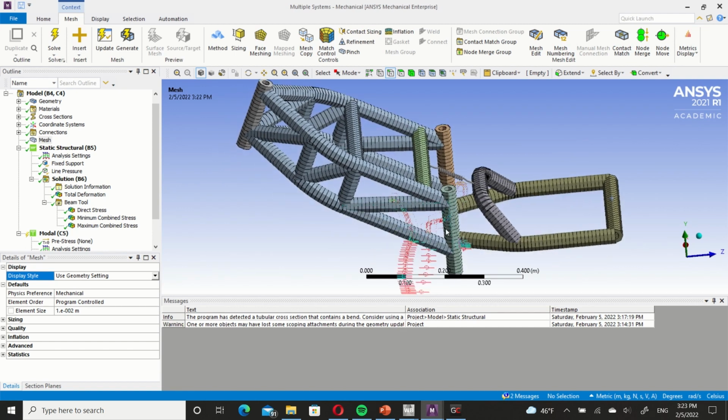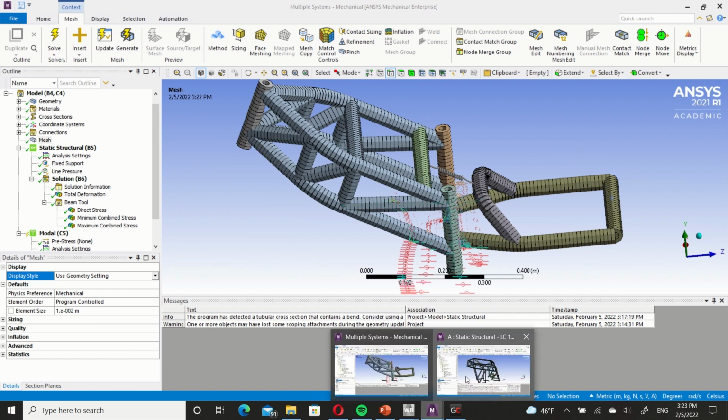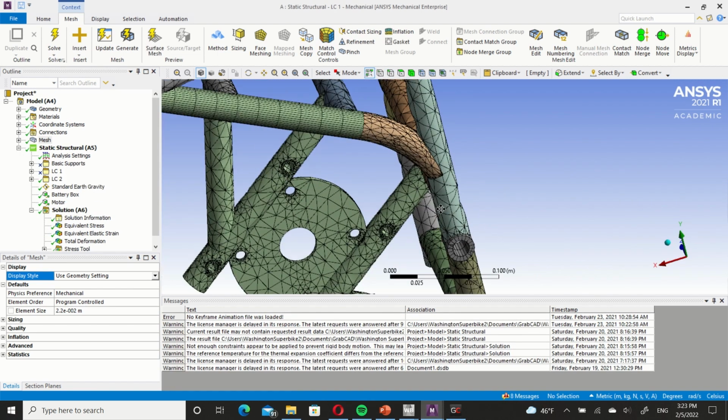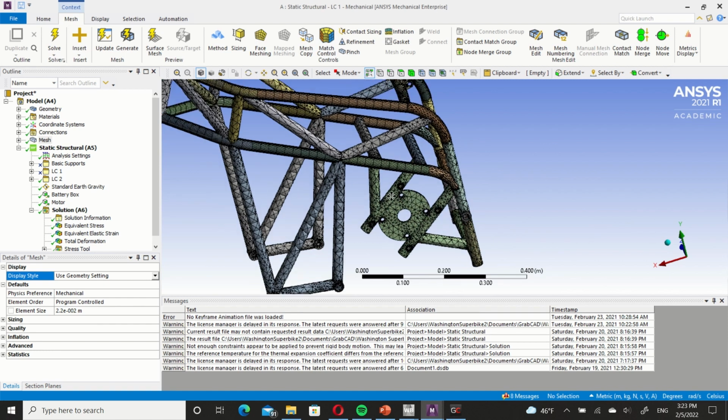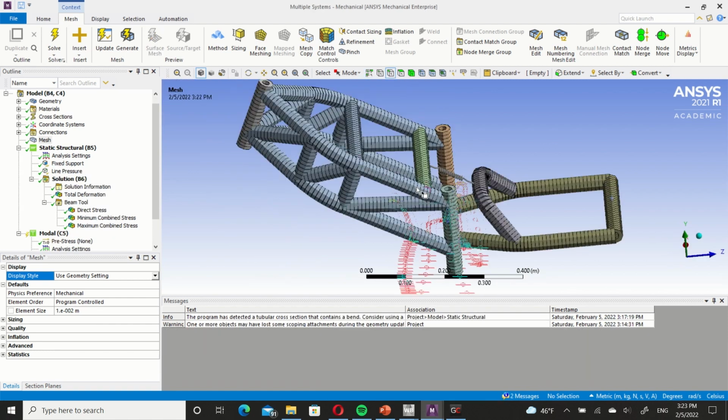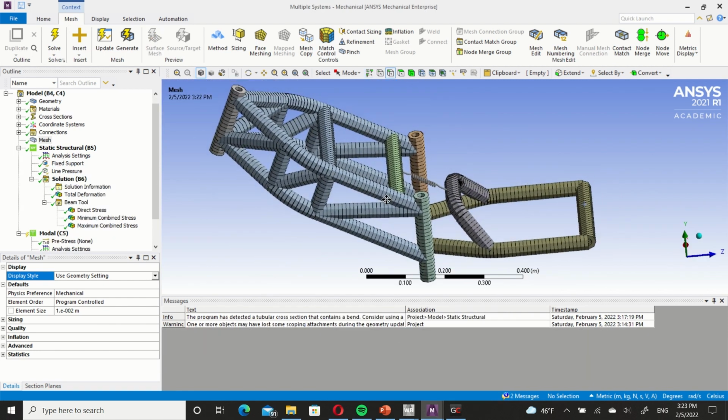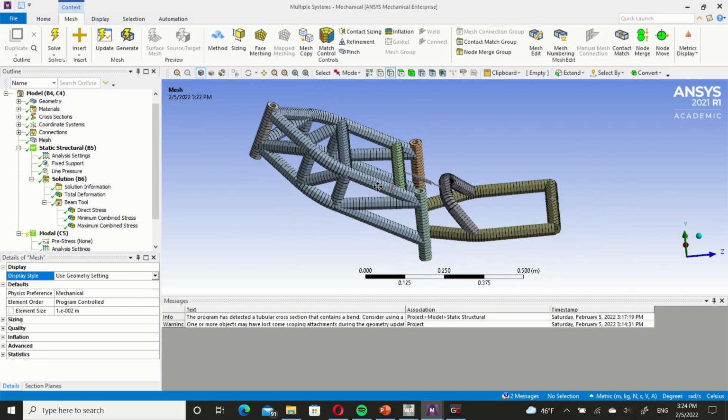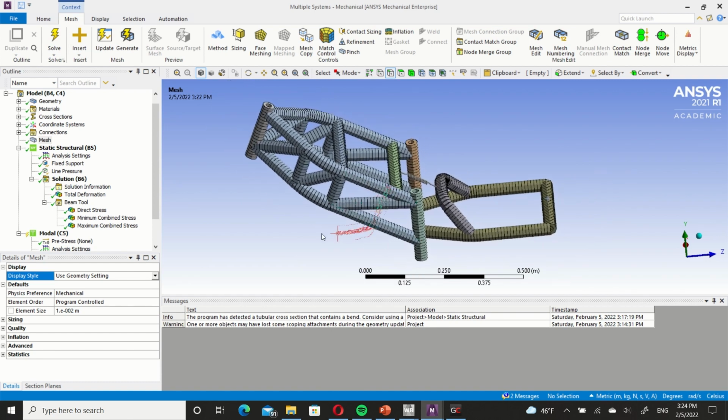Because while this may not factor in all the details in the exact model that this one has, such as this component right here, that penetration, this will have a much cleaner mesh that results in a much more accurate running ANSYS that will reduce those random errors that tend to come up when you have a not so great mesh.